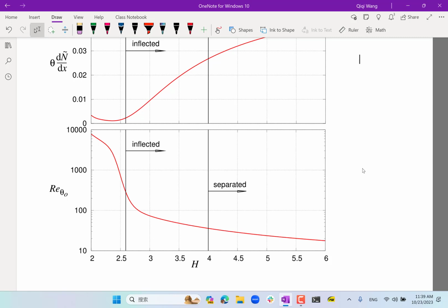One is the Reynolds number. This picture tells you the boundary: below this red curve, any perturbation you put into the boundary layer would not grow in magnitude. Above this red curve, there are certain small perturbations you put into the boundary layer that would grow exponentially. So this really tells you the separation between the two: underneath the curve, it is impossible to have transition, and above the curve, depending on what perturbations you have, you may have transition. All right. So it tells you the two most important things.